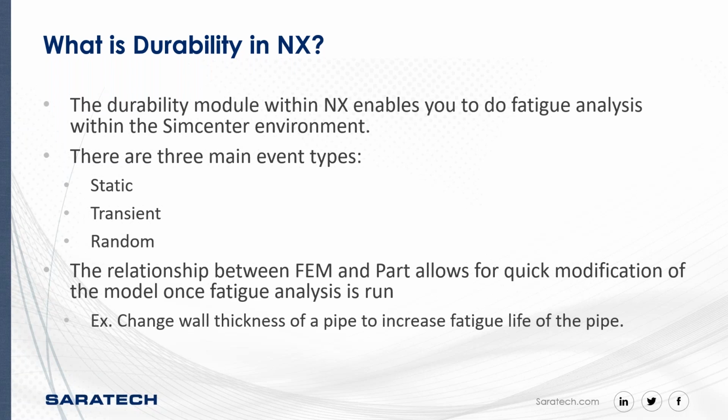Okay, so what is durability within NX? The durability module in NX enables you to do fatigue analysis within the Simcenter environment. So there's 3 different event types that you can do within this durability module. The first one is static, and that's what we're going to be doing today. We're not going to touch the other 2, but the other 2 are transient and then random analysis.